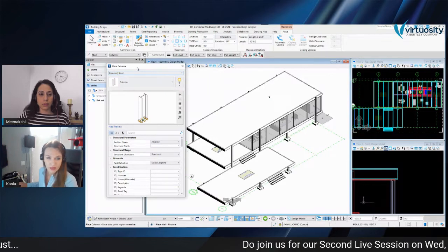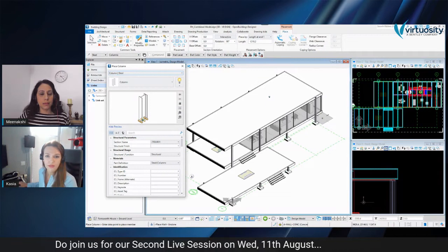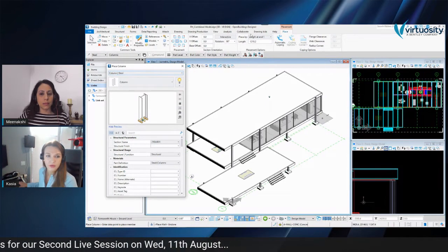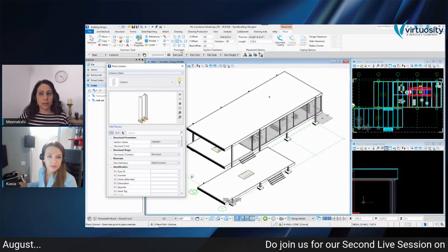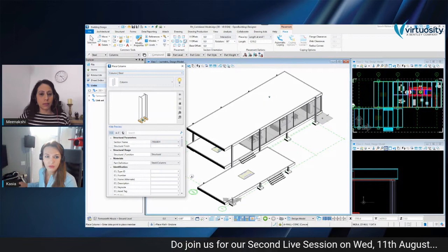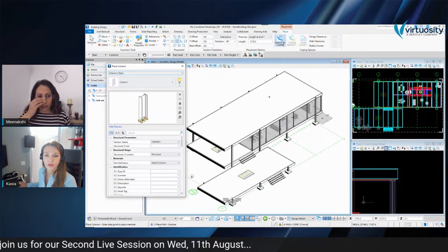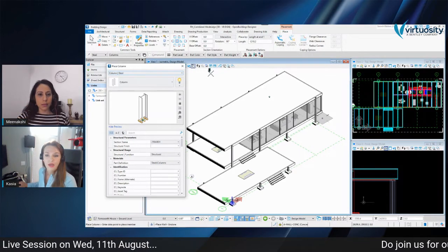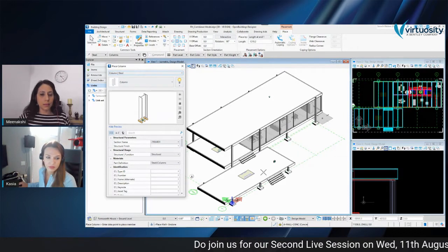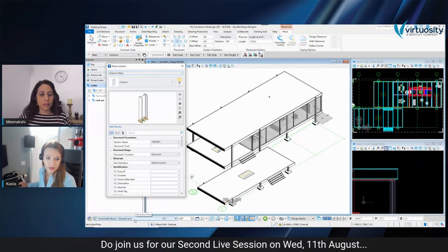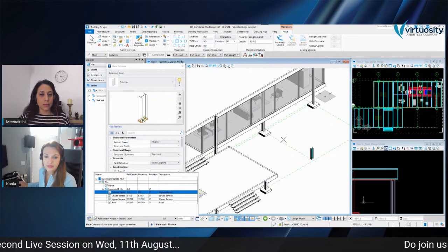So this is the first step always for the majority of the tools, and then the placement tabs that appear in the ribbon tab when we select the element, where we can set the placement point, where we can set the offsets, the rotation, and some automatic coping, for example, for the column. It's how it works. And then, of course, we remember about the floor selector, so about choosing the right level where we want to place the element, and that we can snap to other elements.